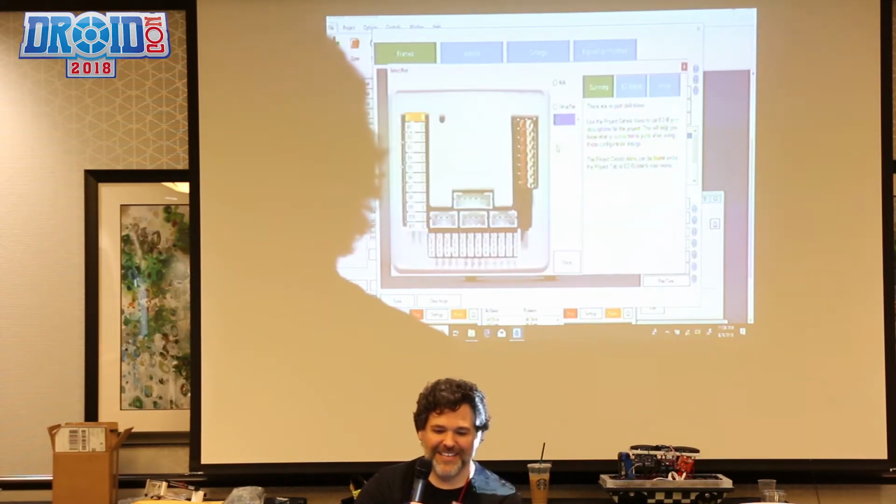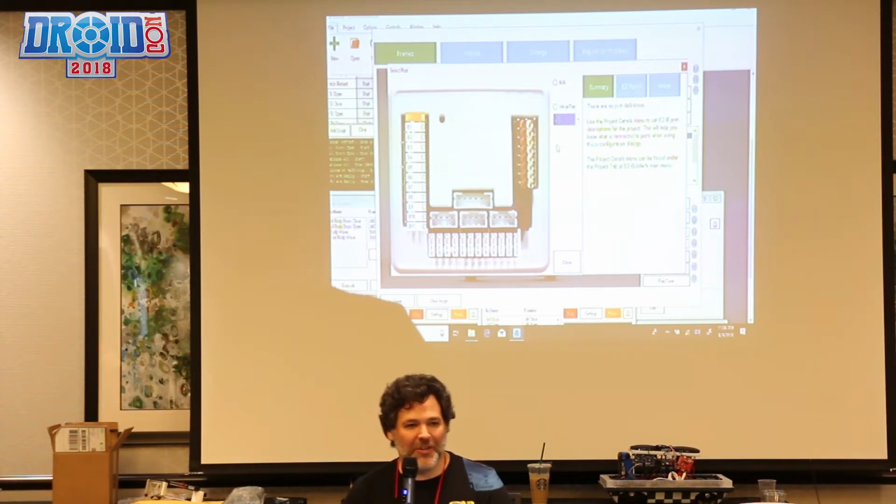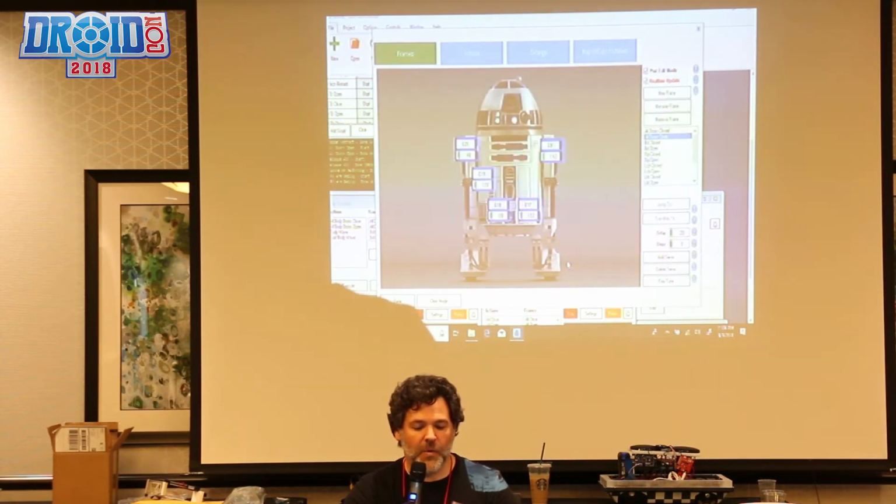So when you're doing this, you can actually pull up the microcontroller and look and see, okay, where's my servo plugged into? Well, in this case, it's plugged into position D0, which is on the upper right-hand side. And then once I got it plugged in, what do I want this to do? Well, this is where your travel piece is, where you can adjust the actual servo position.